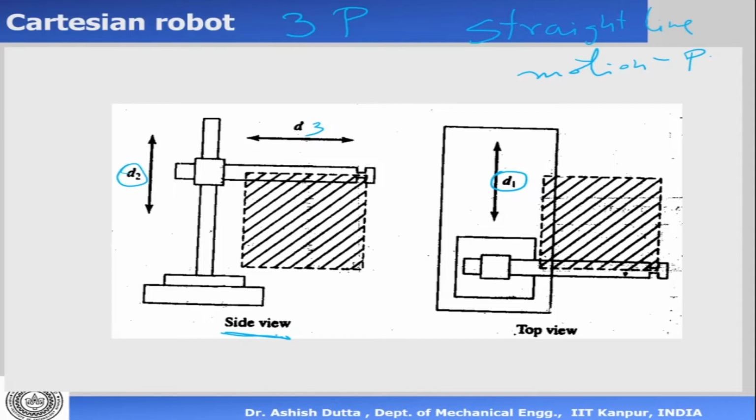Now let us assume that this link is fully extended as shown here. So this is the maximum condition in which it is extended. So it is till here, it can come till here. Now I can move it backwards, the link, when it goes back like this, it will come to this point. So when I'm moving this joint number 3, I'm retracting the joint in this direction. What is happening? This end effector tip is going like this, and it's having a straight line. So which means that any point in the straight line it can go to, right?